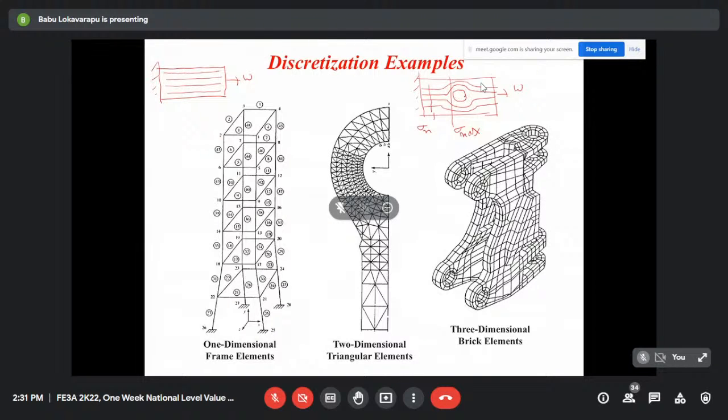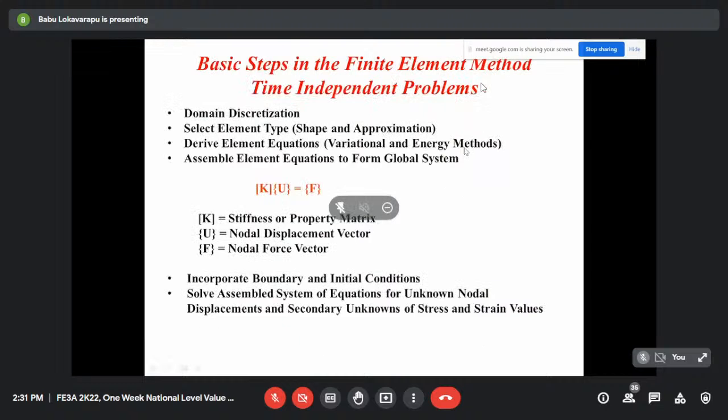So having a hole is very essential, but you should know that when you do the finite element analysis, very close to the hole, you try to use a very fine, very refined mesh. And in the area on the left side and the right side, the meshing is normal. But at critical sections, you take a very fine mesh. Okay, that you can see clearly when you are doing the analysis.